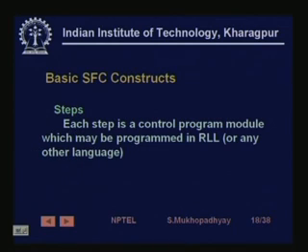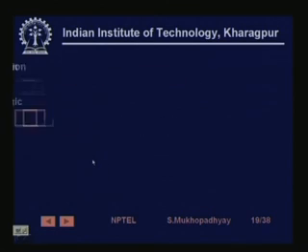They are basically state machine-like constructs and contain some simple programming constructs with which we are familiar. Just like states and transitions, here you have steps and transitions. Each step is actually a control program module which may be programmed in RLL or any other language. As I said, it is a function.